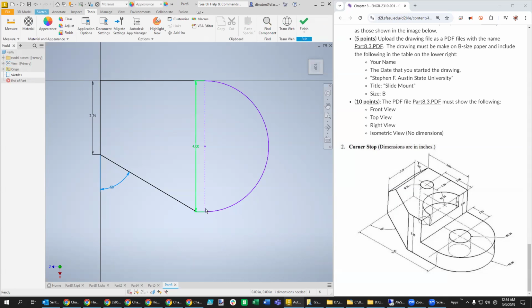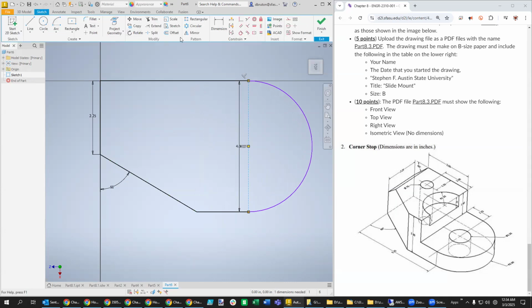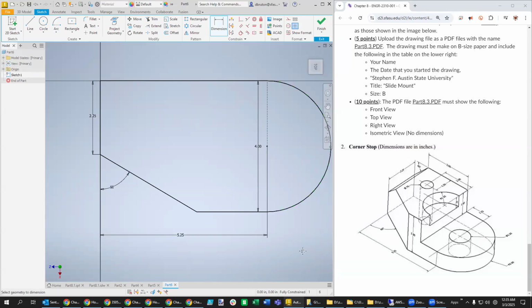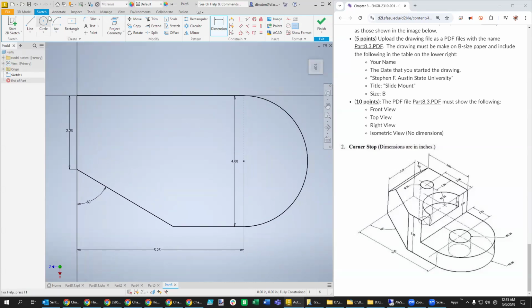All right, now this looks like it went way over there, so we don't even have that distance visible, but we can just stretch it out manually. And then look at the distance right here, which is 5.25. That's from the center all the way over to this edge, 5.25. Is it a fully defined part yet after we get the 5.25 in place? Fully constrained. We want to add everything else that's on the bottom plane, and that would be a cut right there and a circle over here. Let's get some dimensions in there.